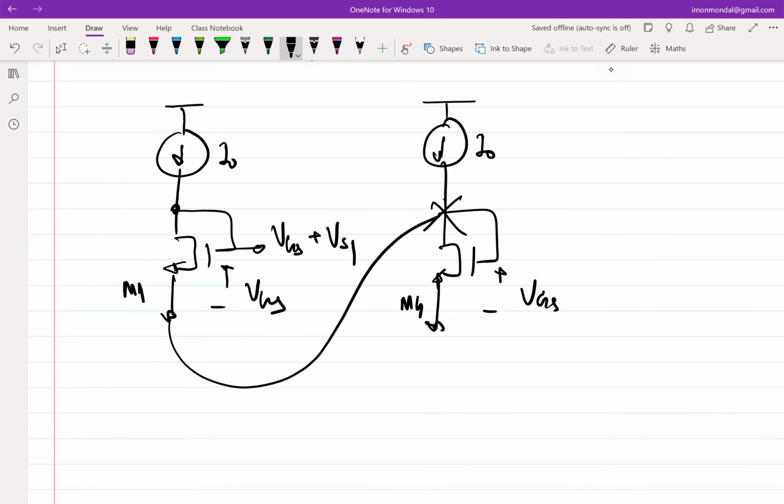Correct? It's trying to, because ultimately the way this has been structured, this is I0. So M4 is now trying to get 2 I0 current. But we don't want 2 I0 current. How much do we want? I0. So I can get rid of one of the I0. Which I0 do you want to get rid of? Top one, right? So I can get rid of this guy. And if I resketch this, this essentially becomes